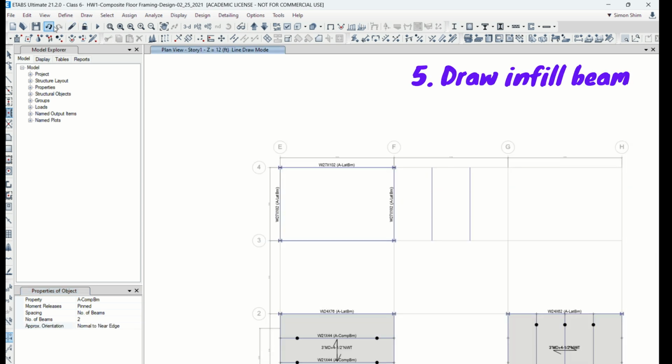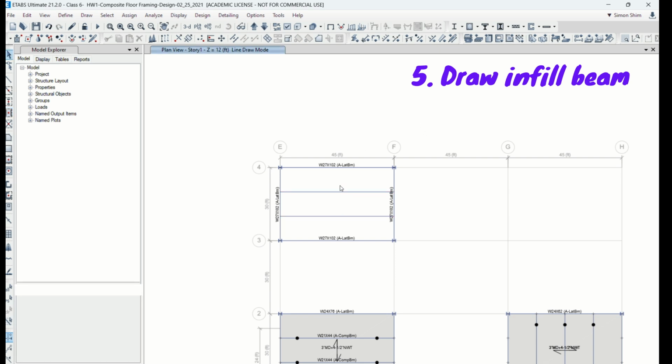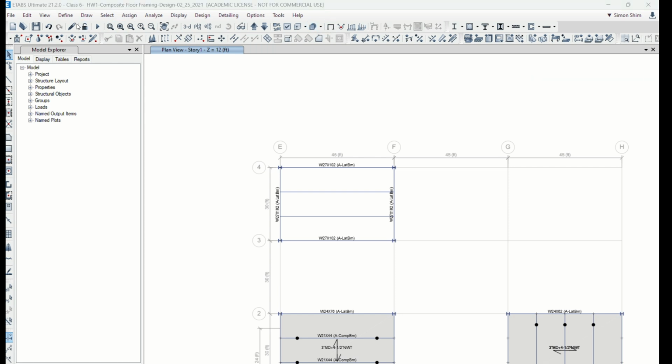Oh, that should be the other way around. Should be Y direction. No. Extraction. Yeah, extraction. Right. You see that when you move over this bay, it shows the dashed line. So I click, then the ESC key. Now I'm going to refresh it. Yeah, this. Okay. Since I chose the pin connection, it shows a dot. It means it's a simply supported connection.